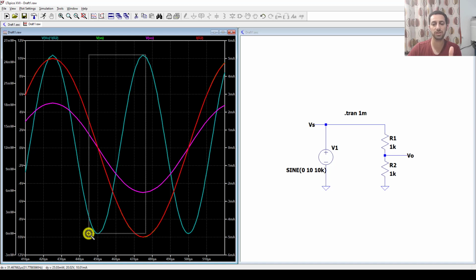So it depends on what waveform I'm interested in. I can get the peak-to-peak value from these three values. For the frequency, the frequency is from peak to peak. You can get the duration. So the duration now is about 50 microseconds, and I can get the frequency by taking the reciprocal of this one.